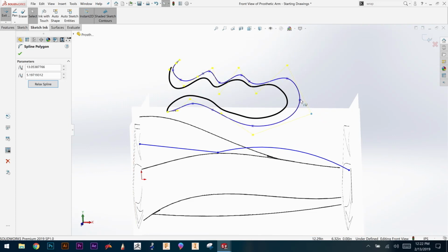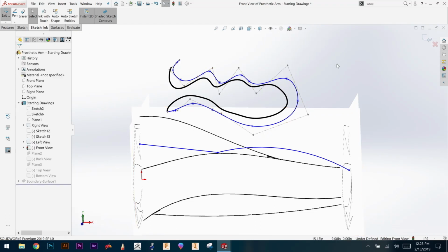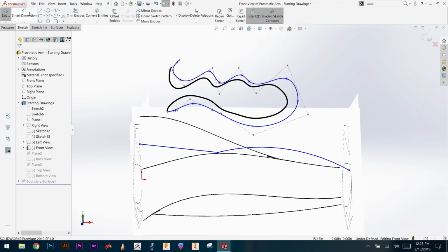You can always still just drag the spline point directly, but using control polygons gives you another handle to control the curvature. And I've found in my own experience that it's a much more intuitive way of controlling the curvature rather than editing the spline points and the tangential arcs or the lines that come off of it to control angle and magnitude. And you can dimension those, right? The control polygons? I believe so. I haven't done that in this model.